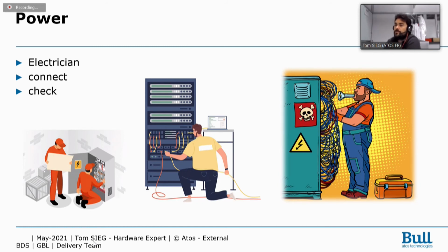So electrical connection is the beginning of the nightmare, because if you have any problem during transport, a little component moving, metal pieces getting into a connection, you will have a short circuit, and it will be at this moment that you generate the short circuit. So again, be careful, take time, check and check again.